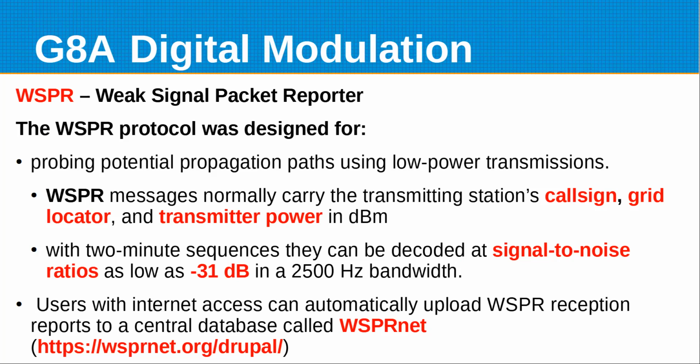And these digital modes like FT8 and the others are basically capturing everything within a normal IF passband, which is like 2,500 hertz for a wide one. So you see every signal in there, and it tries to go through and decode them.